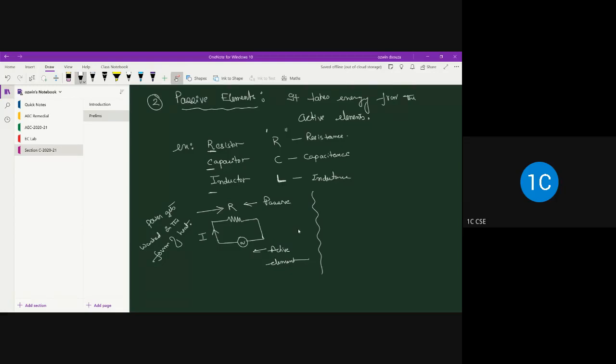So that's the reason you can always compare the quality of two fans. Let's say you buy a fan, some local fan from the open market, which is available for say 200 rupees, and you also buy a good fan, something like Crompton Greaves. Both have the same rating of, let's say, 100 watts. Use these fans for about 30 minutes, and after the usage, just turn them off and start touching the fan domes. You'll be surprised that the Crompton Greaves fan will have lesser heat. On the other hand, your not so good B grade fan will have more heat generated.